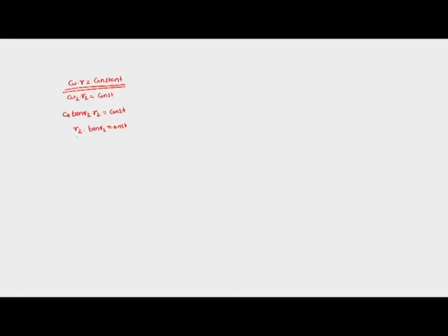If we are at the mid blade height, then R2m into tan of alpha 2m is some constant k, and if I want to work at some other height, maybe R2 dash, then R2 dash into tan alpha 2 dash is also k.